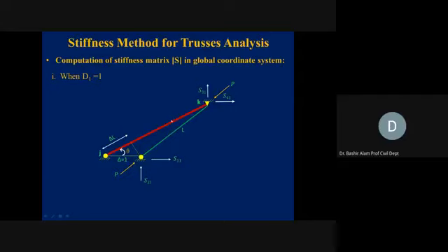It means this member, by this sliding activity, is coming in compression. How do we find out how much is the change in length because of this delta 1 equal to 1 activity? We can draw from this green a perpendicular on this red one, and here we see the change in length. So it got reduced by delta L.